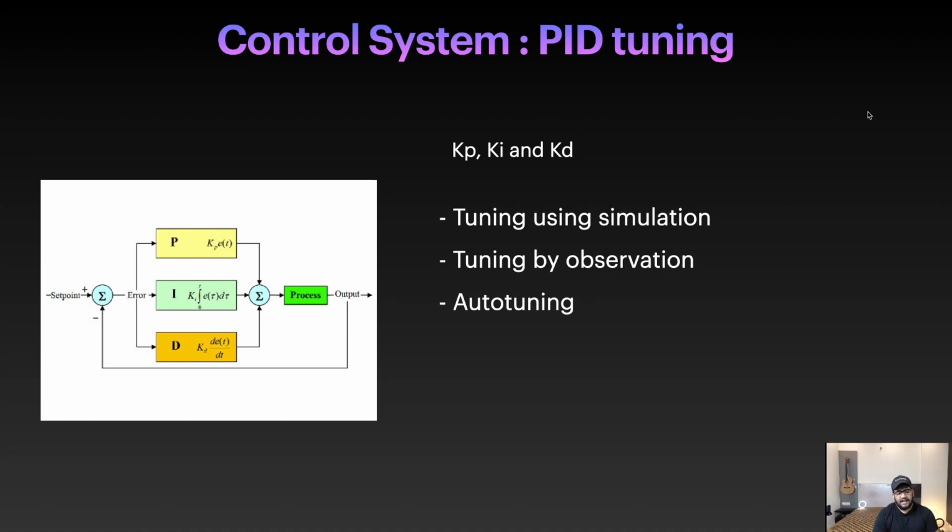Another method that I have not mentioned here is something called black box logging, and I didn't mention it because not every flight controller has an option for black box logging. So what is black box logging? It's basically logging your flight data into an SD card and then analyzing it using software. So you log the data: at what particular instant, what command you gave from the transmitter,